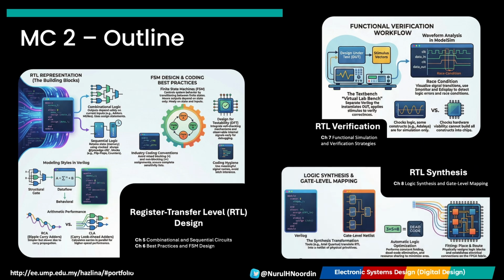Once the logic is flawless, it is time for the heavy lifting, logic synthesis. In chapter number 8, the Intel Quartus tool translates your RTL code into a gate-level netlist, mapping your design directly onto the FPGA's physical resources. But does it run fast enough? That is where static timing analysis, or STA, comes in. We will analyze digital system performance by examining the critical path, setup and hold times, and timing slack.